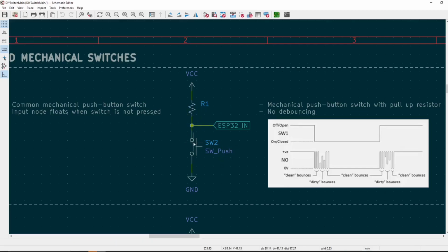So now when our switch is pressed, we will read 0 at the digital input pin as well, but in case the switch is open, via this pull-up we will have VCC applied to our input pin, and in this case we would have a 3.3 volt readout.